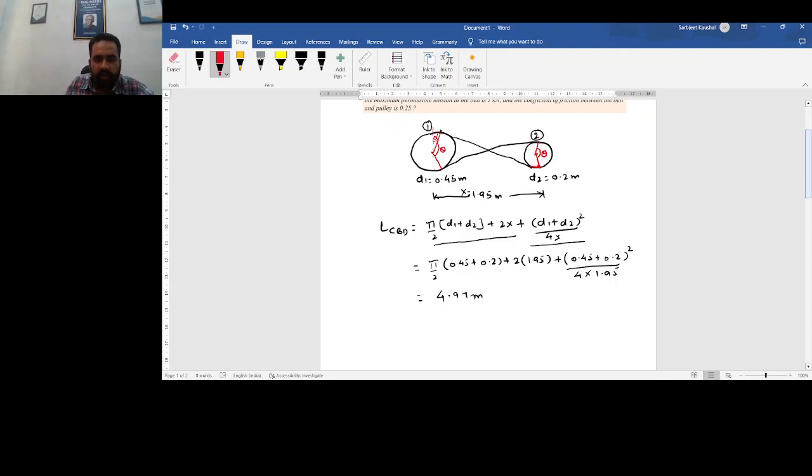So all of us know that for a cross belt drive, sine alpha is equal to (R1 plus R2) over X. This equation we have already derived in the case of the length of the belt drive. We can also write it as (D1 plus D2) by 2x.